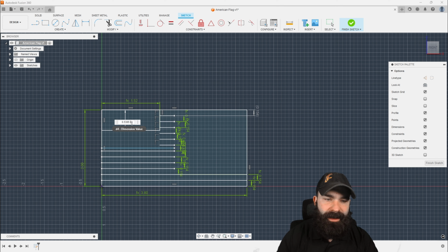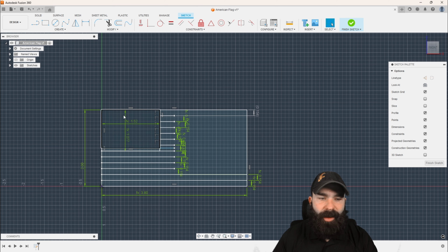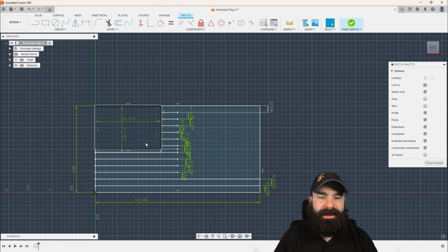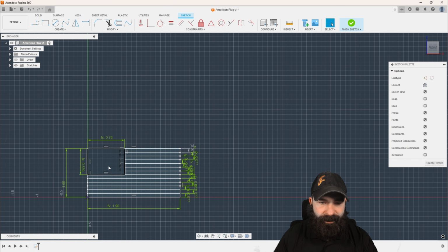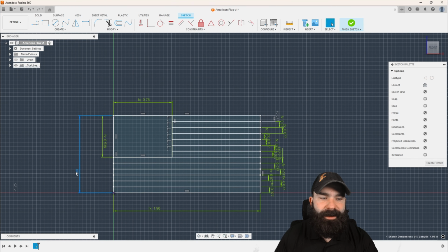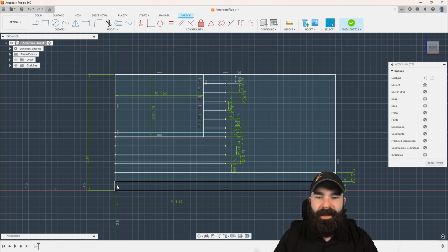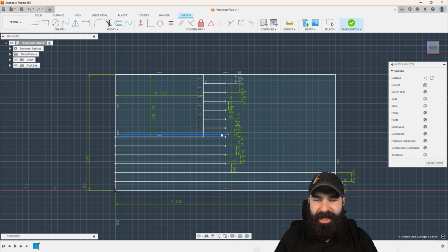Again, we could do that here. We're going to take this guy times D1, automatically updating the size of that rectangle as we need to reflect the proper values. So as I go back to 1, you're going to notice we shrink back down to the perfect size. If I go back to 2, everything expands out. We actually have an extra line floating in here that we don't need. So let's delete that, and now let's drag these all over and get them constrained to the side.